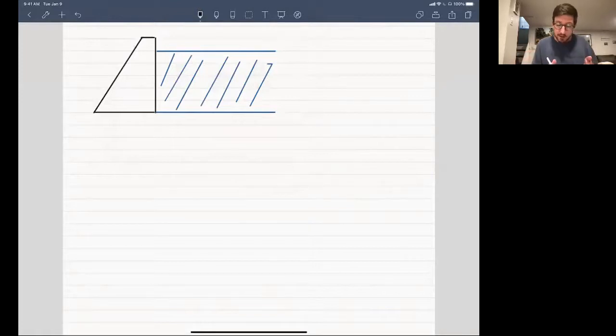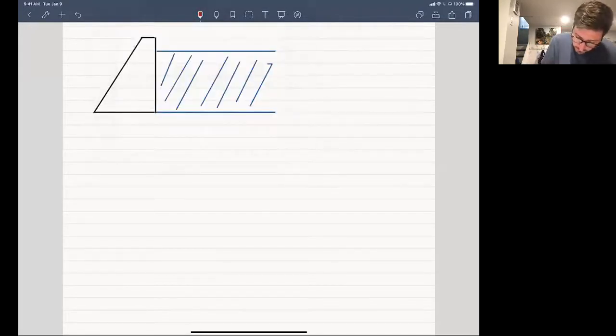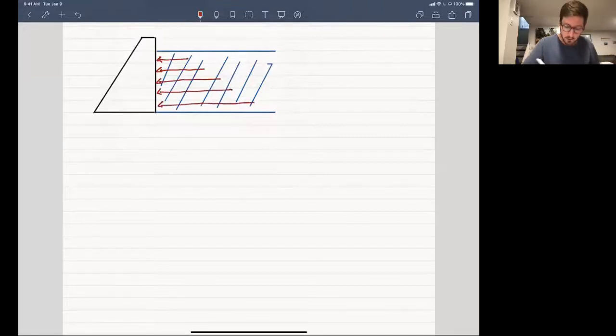And what you can see from my little picture here is actually characteristic of something we do in real life. When we build a dam, we have to make the bottom of it thicker. And this comes from the fact of what I just said, that the pressure that's exerted on this dam by this standing water that it's holding becomes stronger the further down you go.